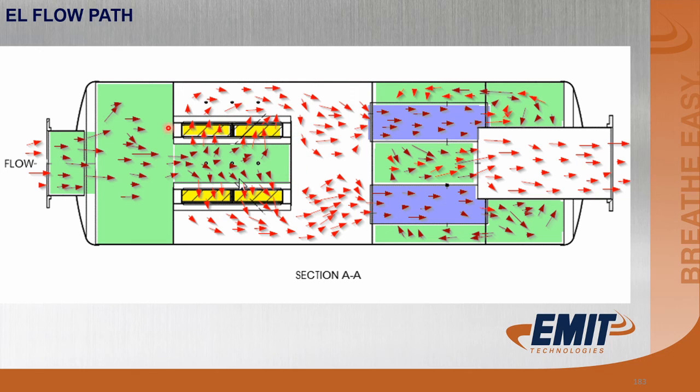On these particular housings, you don't necessarily have to run all the elements that there's slots for. You could put blanks in these units up here and only run elements in one side, until you needed further emissions reduction, then you can add more elements. But in this situation, you're going to have to run blanks or elements. One or the other has to be in these slots.